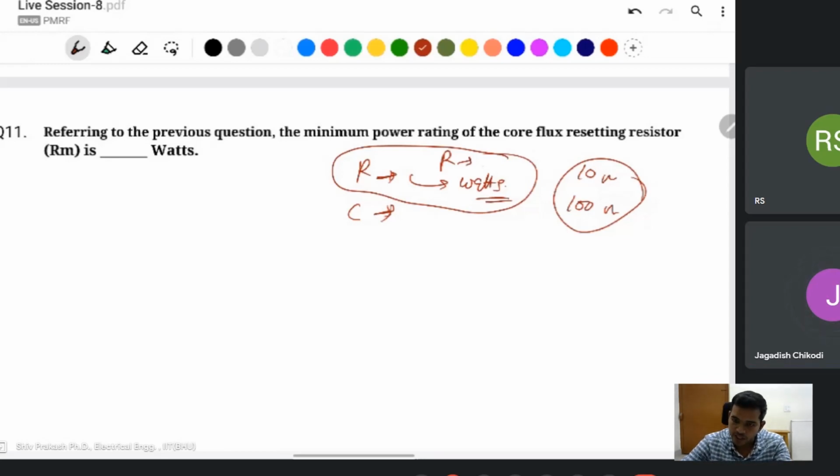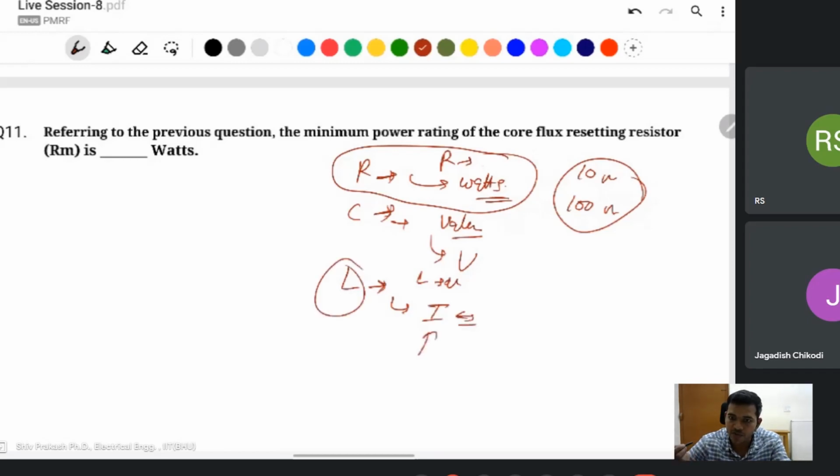If you go to purchase, they ask you for the wattage value of a resistor. In the capacitor case, the value of capacitance comes with a voltage range. What is the voltage range of a capacitor? For an inductor, it is the same: the inductance value is okay, but it also comes with a current range. What is the value of current before the inductor goes into saturation mode? It comes in both RMS value and peak value.